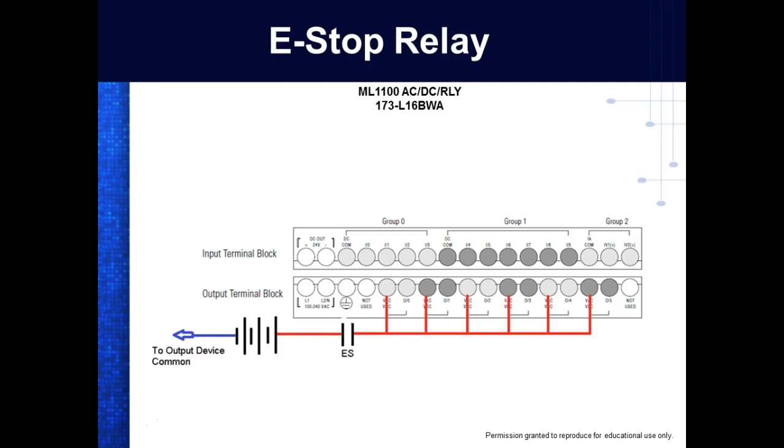These guys run on 120 volts AC. Okay? All we do is just run a power cord into this, or if you're in the field, it would probably be hardwired to 120 volts. We make sure we run a ground, right? You understand that. Then it has a 24 volt DC power supply.